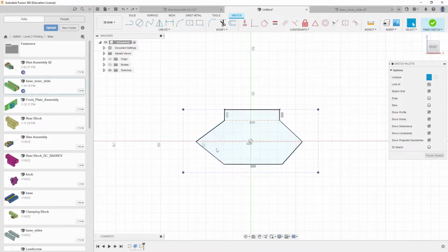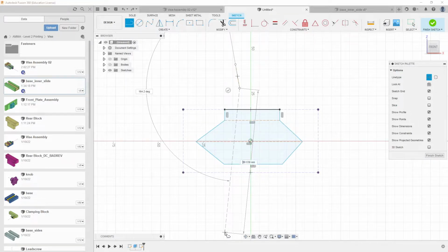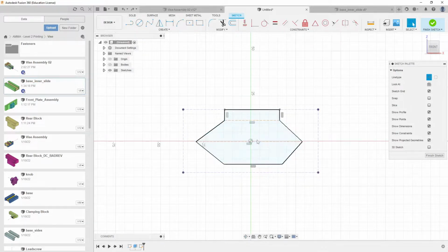So then, like I said, we know that these ones here are going to be symmetrical across the center line here. So I can pick a line tool again, and sometimes I make the line go through the whole part because it's easy to see. But if I know I just need a mirroring element, it doesn't have to be any length. It just needs to be there. So I pick it from here, and then I'll just snap it right to the midpoint right up there. And now, even though these ones are down here, it's okay. I can still make them symmetrical across that line. So I can pick this one here, that point, and that point, this point, that point, and this one, and this one.